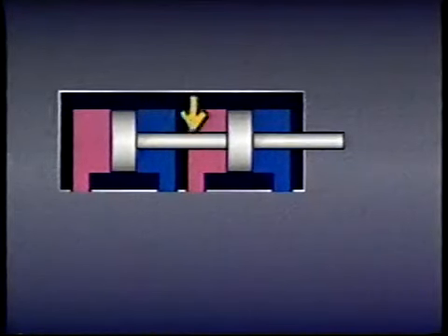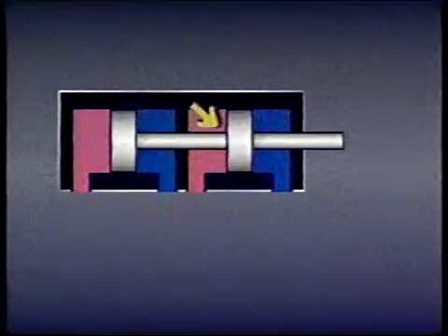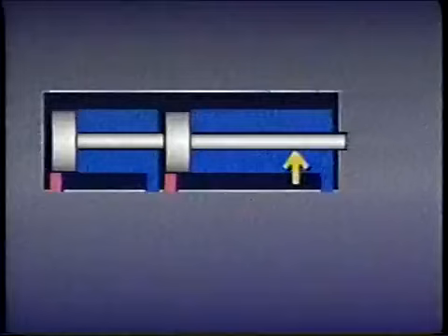Tandem cylinders have two or more pistons connected to the same rod. This allows system pressure to be applied to each piston, increasing the force the cylinder produces without having to use a cylinder with a large diameter piston. Unlike tandem cylinders, where the pistons are joined to the same rod, the rods in a duplex cylinder are not connected. Each rod has a different stroke. This allows the load to be moved to several positions.